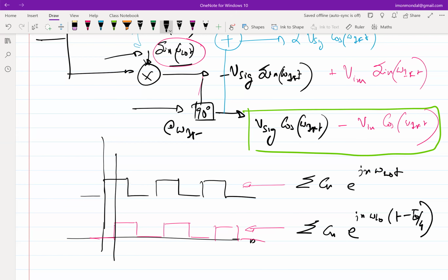But if you start off with double the frequency, then you see there is some event happening at the edge of the clock. So then you use a D flip-flop to delay the initial clock, and then you divide by 2. Divide by 2 is basically using a counter. So you get a delayed version.